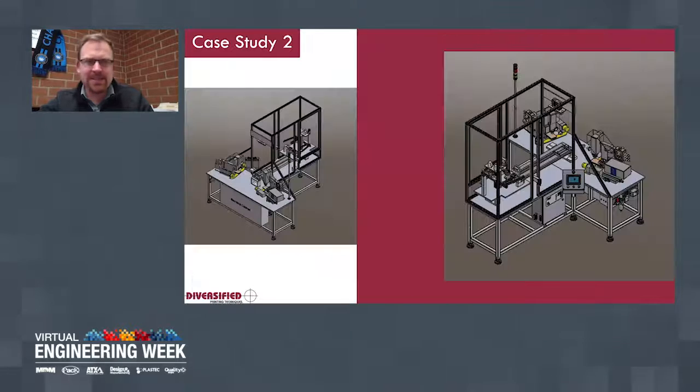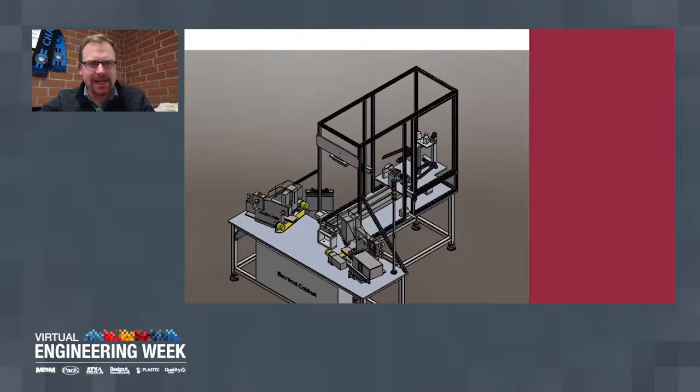This great case study here, they're taking parts, putting them into this cell straight from the robot. We have locking mechanisms on the fixture to lock that part before the robot lets go. We have actually a pad here that's working to hold the part down while the printing's happening. So that's just kind of a hold down pad. And then these are neat machines.